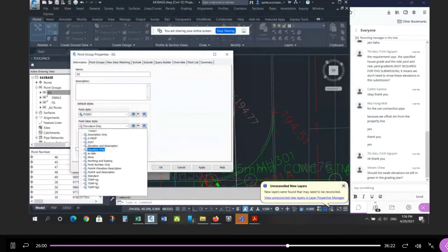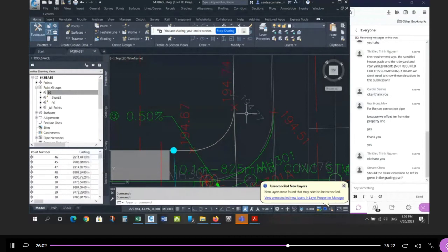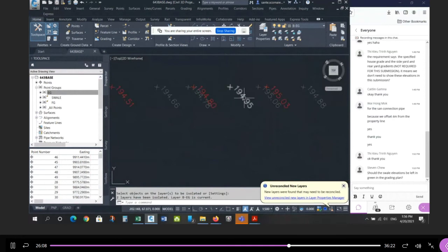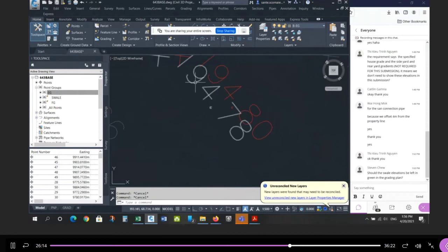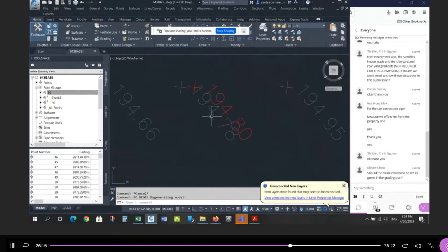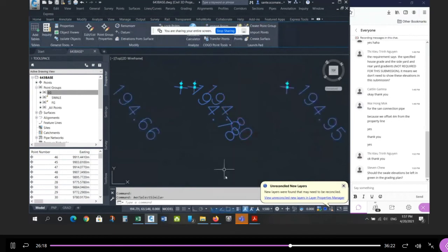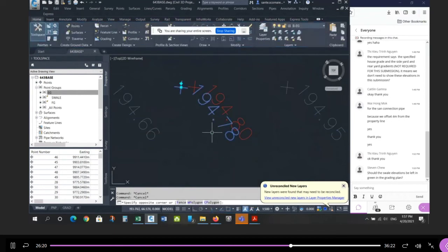Oops, not the point, the existing elevation. So now they're the same, but 75%, right? If you compare these, the existing is 75% of the design. This is 2 millimeters high. This should be 1.5 millimeters. And if it's not, select similar, it's because, whoops, these ones here.